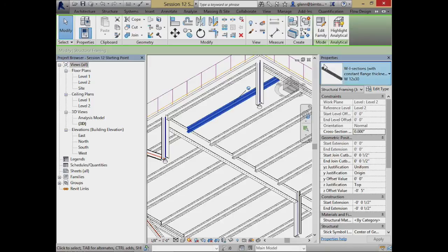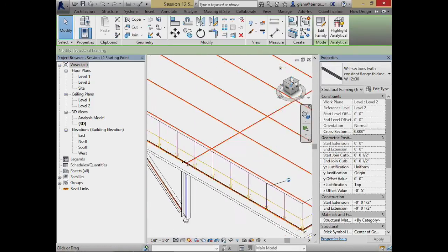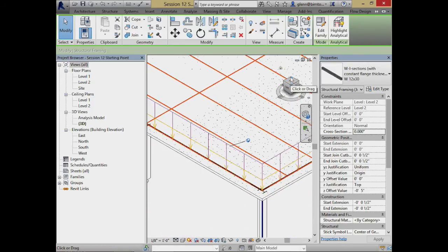So why did we do all this? It was really, now that we have that structure figured out, we can, in our BIM model, have accurate sizes so that we start placing ducts and pipes and everything that we want around them. And that's really the intention behind this whole workflow, is that you can have a BIM model and a structural model working together and have that bi-directionality in terms of what's going on.